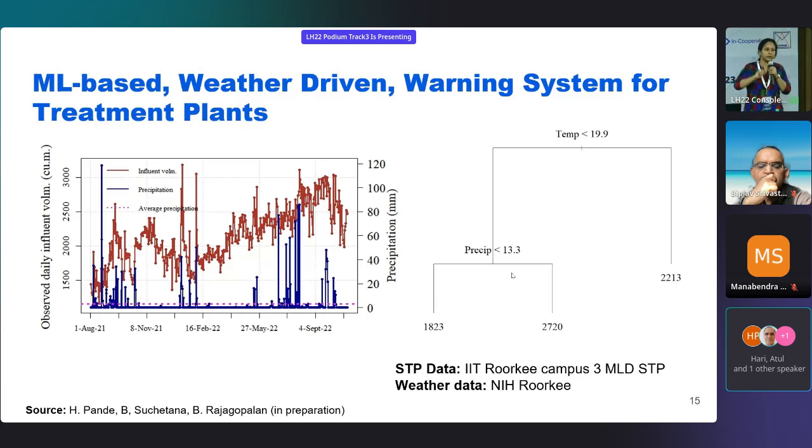More importantly, the wastewater treatment plant at the end of this pipeline or this network is not designed for that. So now we are bringing unexpected stormwater loads into the wastewater treatment plant as a result. So this is the problem that we were trying to look at.